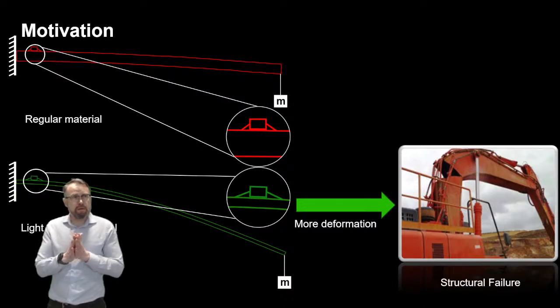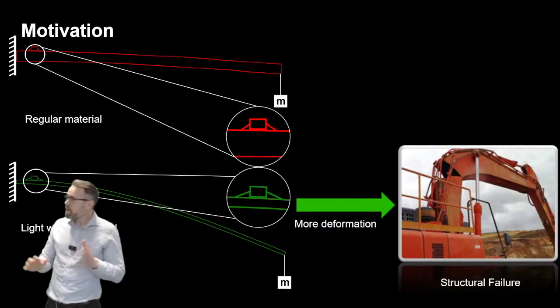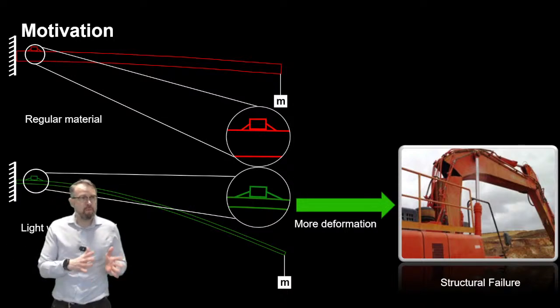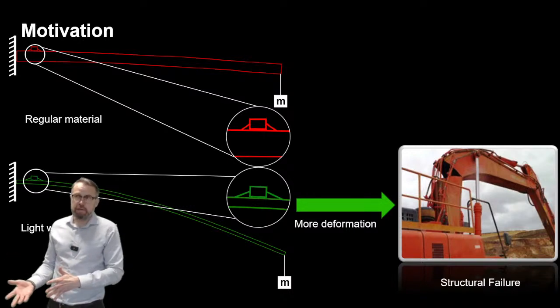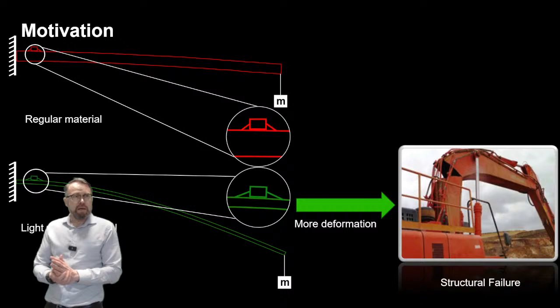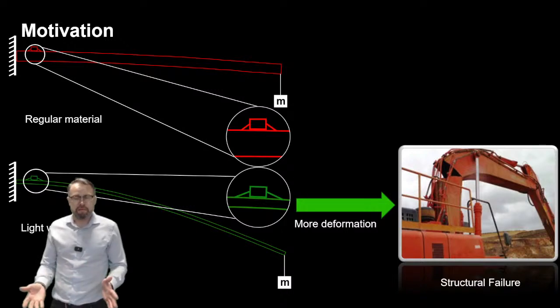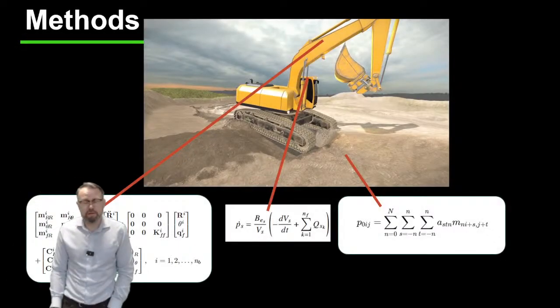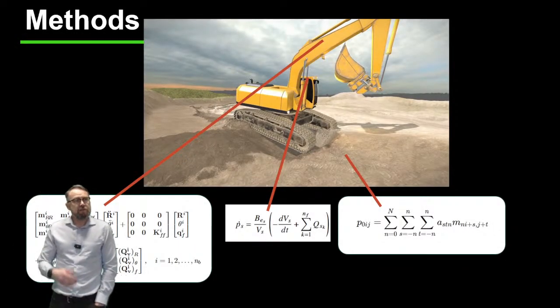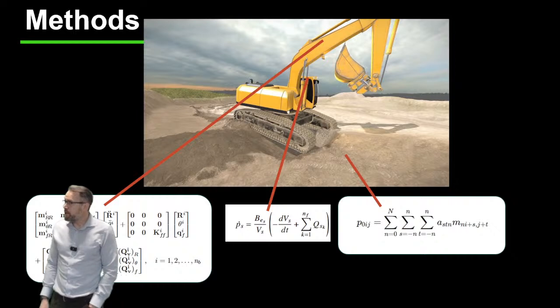Now, typically, when you're building heavy machinery, you're combining components together using welding. Welding comes with the problem that, due to the welding process, there are going to be initial cracks and high residual stresses. Once you know the material, which is going to be steel here, the geometries of the joint, and the loading, you can make a prediction of fatigue life. What's hardest is knowing the stress history. And this project will introduce a concept that helps to create a better understanding of the stress histories that are loading the joints in heavy machinery.